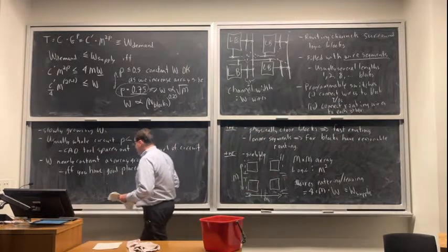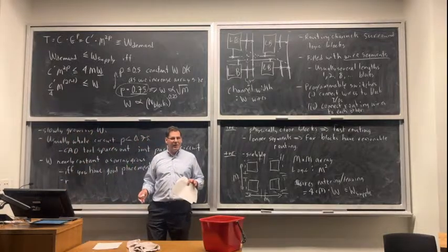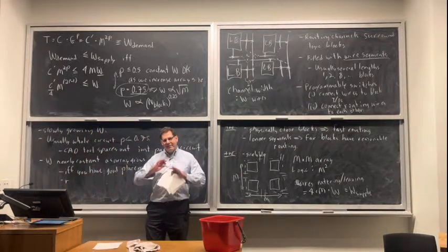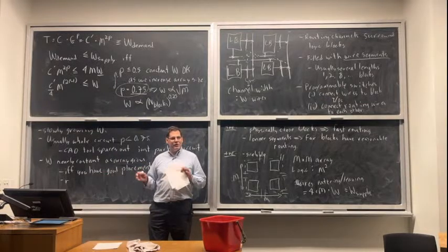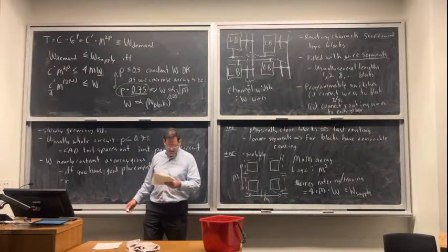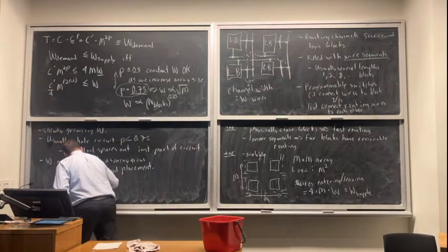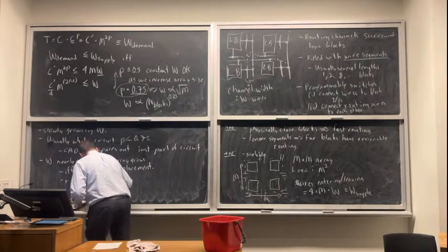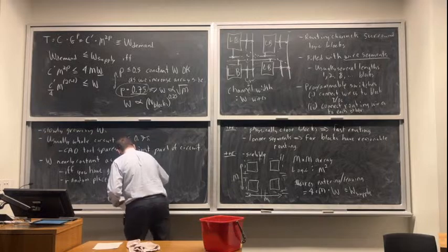If you have a random placement, let's say you just decide, I don't want to invest in good placement, I'm just going to work on the hardware, we'll sort out the CAD tools later. It's actually a relatively common strategy for startups, but it's not a good strategy. If you have random placement, then your Rent exponent is approximately 1.